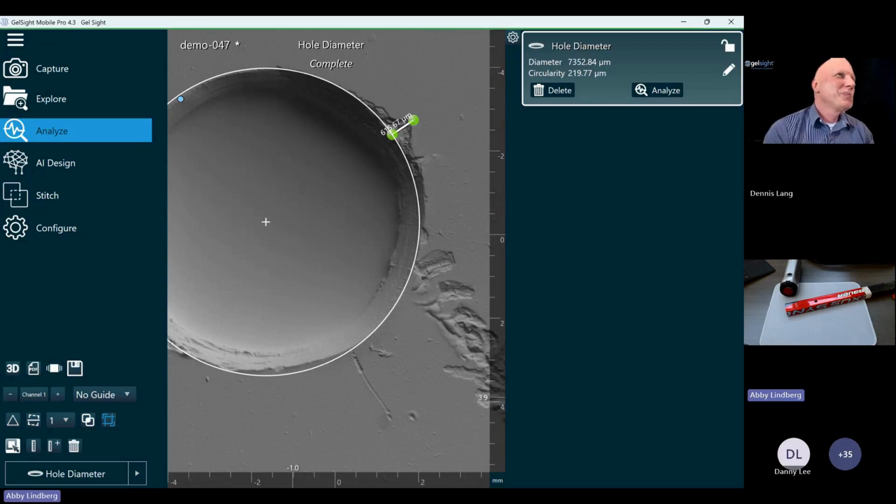So, yeah, exactly. Another thing to point out here, which you touched on when we talked about different materials, this is obviously very different materials between the layers that we're seeing, and with other optical systems, this might require multiple light settings, multiple light levels, and scan stitching to get that kind of data on the surface to minimize those data dropouts. It can be a lot of time, especially having to take scans of the same place over and over with different light settings.